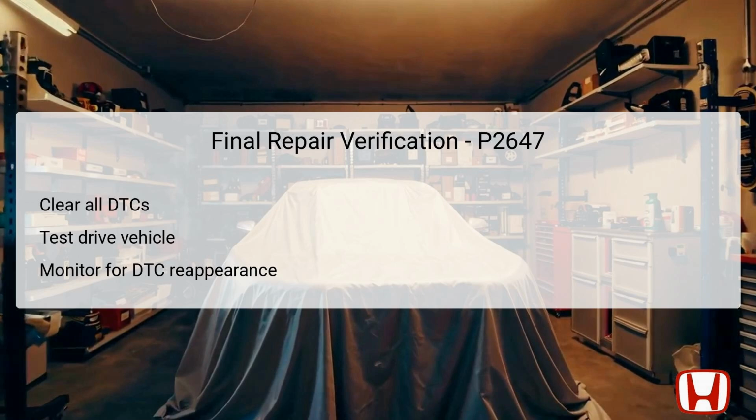Following the completion of all troubleshooting steps, it is crucial to verify that repairs are successful. Begin this process by using the HDS to clear all diagnostic trouble codes from the system. After clearing the codes, take the vehicle for a test drive to ensure that it operates smoothly without returning to the initial fault conditions. During the test drive, pay close attention to performance issues and monitor the vehicle's behavior.